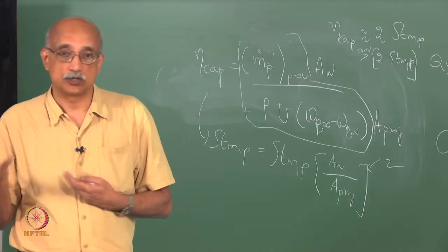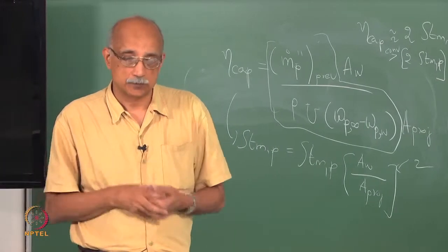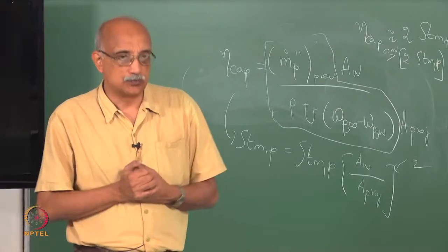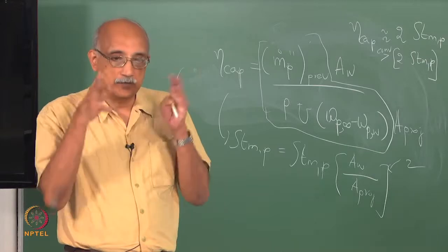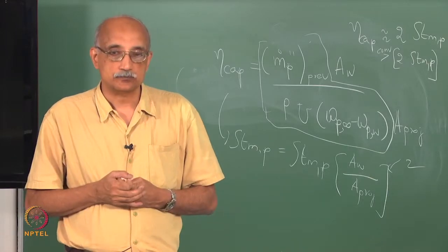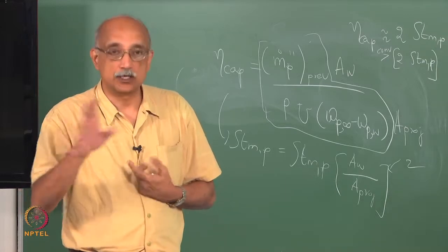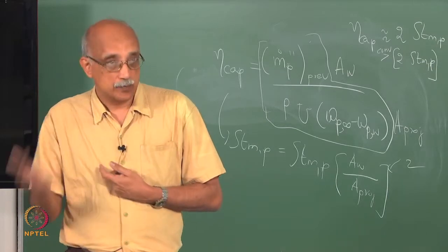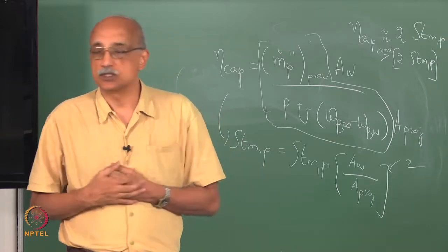For example, we talked about discharge from silos, where when you open the gate, you want the material to flow like a solid block, and you want it to behave in a very, very predictable way. Whereas, if you are trying to pump a slurry through a pipe, you want to minimize pressure drop, and pressure drop increases as cohesion increases.